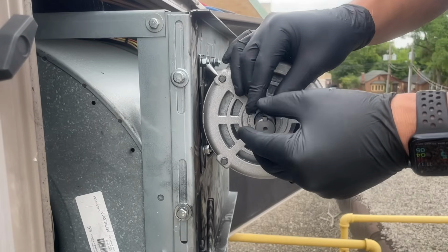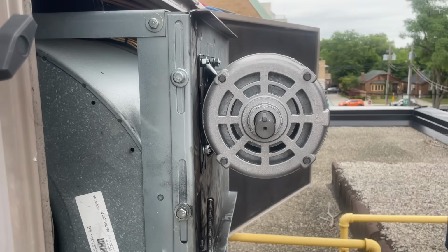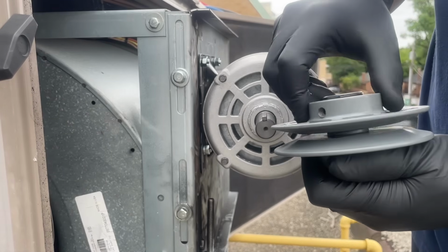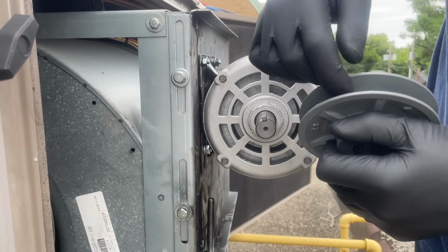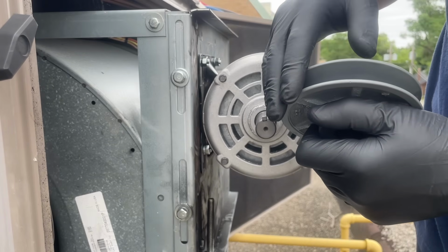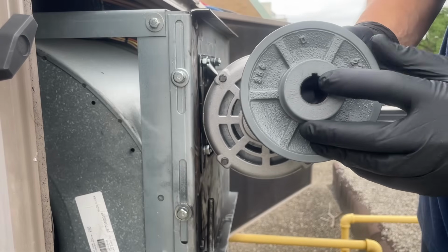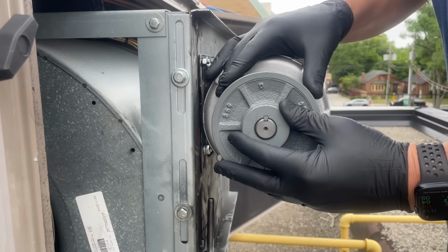Now you'll need your machine key. This came with this brand new motor. If it doesn't, you can buy an assorted pack. You can buy a stick of it in fixed sizes, which come in like 2 or 3 feet. In this case, we have one. And then you'll take your pulley. So we have our belt adjustment side. The looser you make it, the deeper the belt will ride, which will actually lower your amp draw. If you tighten it up, the higher your belt will ride, which will increase your amp draw. Anyways, this pulley has a groove in it here, and that just should slide onto this new motor shaft like butter. Beautiful.